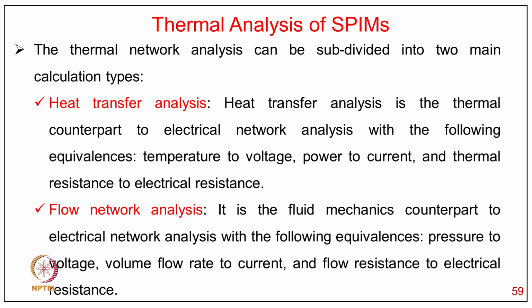Then there is of course the computer used for thermal analysis of the single phase induction motor. Thermal network analysis can be subdivided into two main calculation types. Heat transfer analysis is the thermal counterpart to electrical network analysis with the following equivalences: temperature to voltage, power to current, and thermal resistance to electrical resistance. Flow network analysis is the fluid mechanics counterpart to electrical network analysis with the following equivalences: pressure to voltage, volume flow rate to current, and flow resistance to electrical resistance.